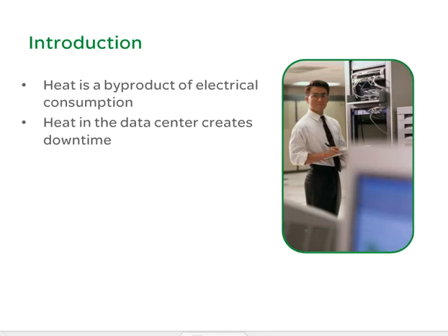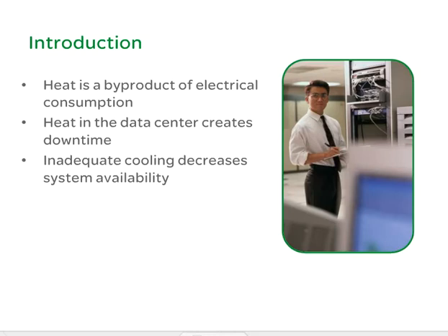Data center and IT room heat removal is one of the most essential, yet least understood, of all critical IT environment processes. Improper or inadequate cooling significantly detracts from the lifespan and availability of IT equipment. A general understanding of the fundamental principles of air conditioning and the basic arrangement of precision cooling systems facilitates more precise communication among IT and cooling professionals when specifying, operating, or maintaining a cooling solution. The purpose of precision air conditioning equipment is the precise control of both temperature and humidity.